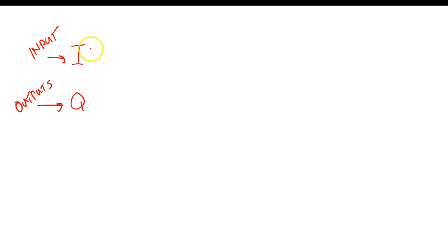Then what we do, we put a byte number. Then we put a dot, which in RSLogic 500 is addressing a word, but in Siemens S7 it's addressing a bit, and then we'll put a bit number. So this is a bit number.